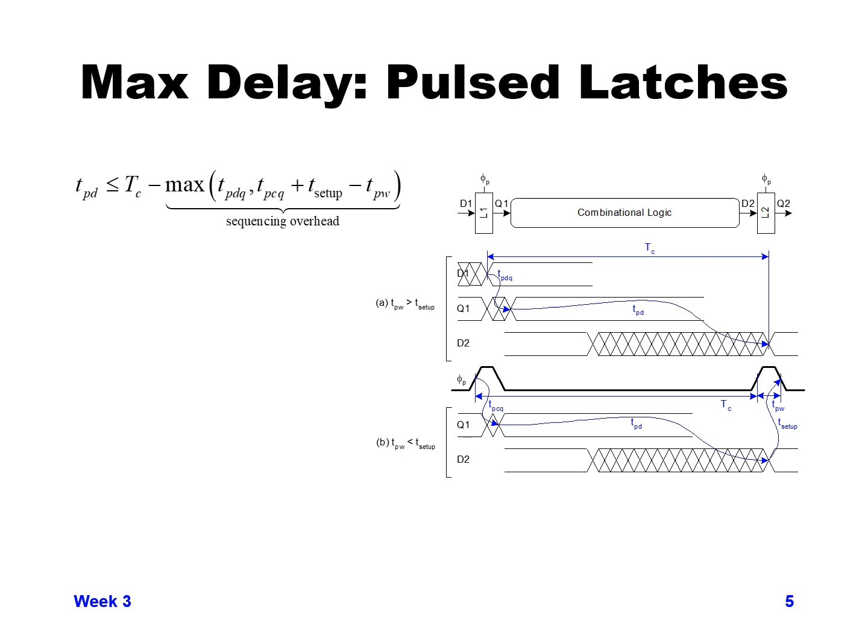Now when you look at the bottom one in the B row, if our pulse width is less than our T setup, then that means we need our data there before the rising edge of the clock opens the latch for the pulse latches for either L1 or L2, because we're setting up to the falling edge. But since the setup time is greater than the pulse width, we need to be there before the clock rises. So this implies data is there first, clock is done after data is stable. So our propagation delay is now from clock to Q.